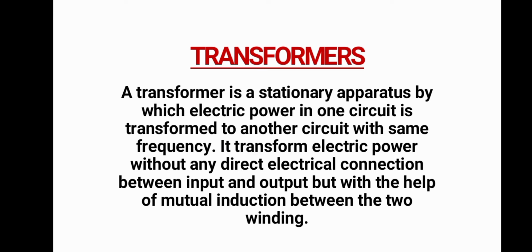Transformer is a kind of static electrical machine which transfers electric power from one circuit to another without changing the frequency. And there is no direct electric connection between the input and the output. Actually, it transfers electric power with the help of mutual induction.